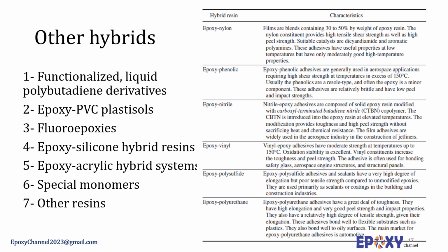In one instance, the hybrid takes the form of a film in which the acrylic, the monomethacrylate of diglycidyl bisphenol A, has been polymerized by UV light. The epoxy is a diglycidyl bisphenol A dicyandiamide curing system containing a polyvinyl phenol amine complex. After irradiation, the film has good tack and will adhere to oily steel. It can be cured at 180 centigrade for 30 minutes to achieve final strength.